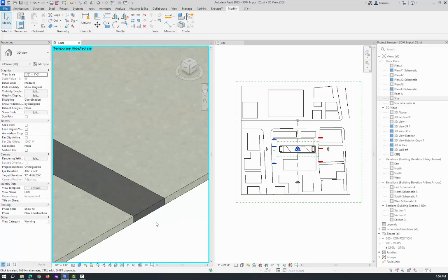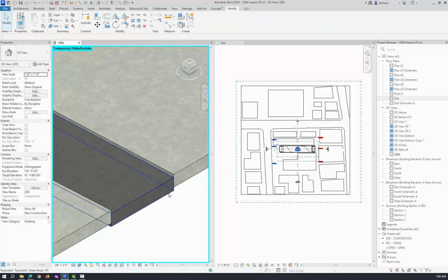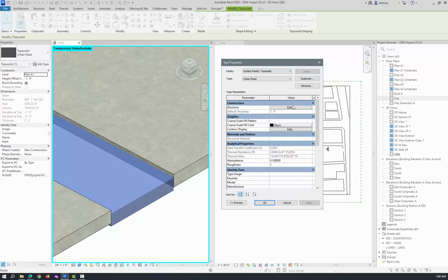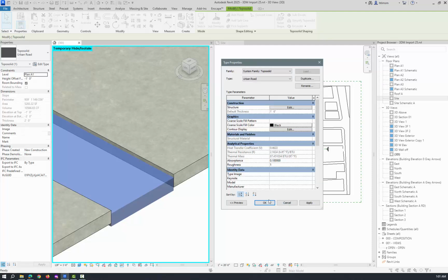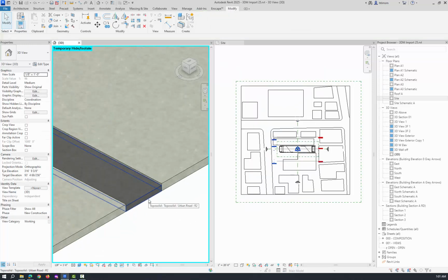Now it would be nice if it was recessed, right? So if I pick that, if I want it recessed another 6 inches, then I'll just do -1, right? So now that pushes down. Now it's a little shorter than the topography, like it pokes out. So I can go in and edit that type, and under the structure, it allows me to change the depth of that. So if I do 1'6" and click OK and click OK, I can do that. Now it's a different color.